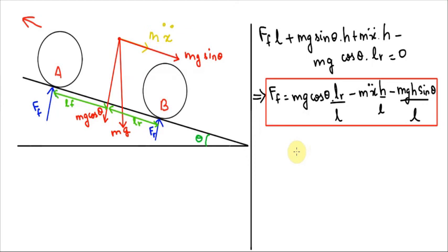Now, this free body diagram does not hold true just for bikes. It also holds true for motorcycles, and even for four-wheelers. Even for four-wheelers, you can develop a similar kind of free body diagram, and this is one of the most important topics when you talk about automobile engineering, that is the free body diagram. From this, there are many things to consider, like the height of the center of gravity, the length of the wheelbase, and so on. So from this you can also know many things if you really have a deeper look into these equations.